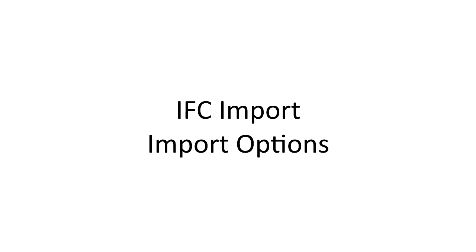Next, we will look at how to import an IFC model into ARCHICAD. In ARCHICAD, we can decide whether to: A. Open the IFC file as a new or a standalone project. B. Merge the IFC or parts of it to our existing project. Or C. Place a model as external reference into the existing project.